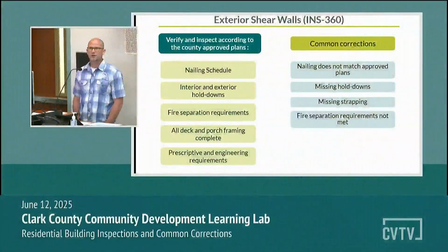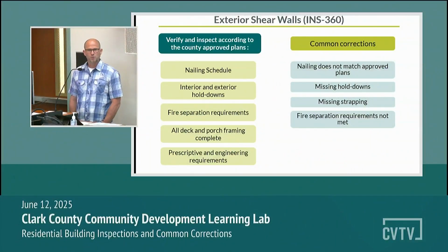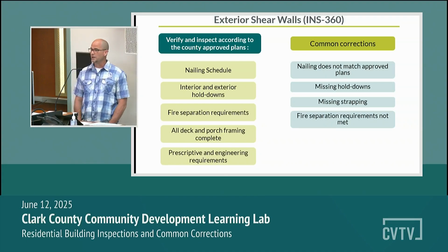There are 3 main things that are beneficial for a shear wall inspection. We want to keep the building from sliding off the foundation. We want to keep the building from racking, and we want to keep it from tipping. Now, some of the things that we talked about back at foundation, the hold downs, are going to come into play now. Some of the things that James talks about at the post and beam with the sill plate and the anchor bolts are now going to come into play as part of the shear wall inspection to keep us from tipping, racking, and sliding.